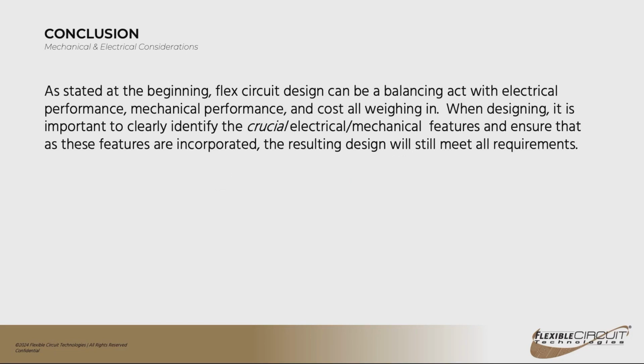So really what you're going to find is flex circuit design is going to be a balancing act. Your electrical and mechanical engineers may not get exactly what they want. Everything has to weigh in and everything has to work. And so you may find that you may not get absolute flawless electrical performance in order to get the mechanical features to work and vice versa. So really what you have to do is clearly identify in your design what are the crucial electrical and mechanical features that you really need. Ensure that you meet those and then give some slack on some of the other features so that you can meet all the requirements and make all of them acceptable and get a successful design.